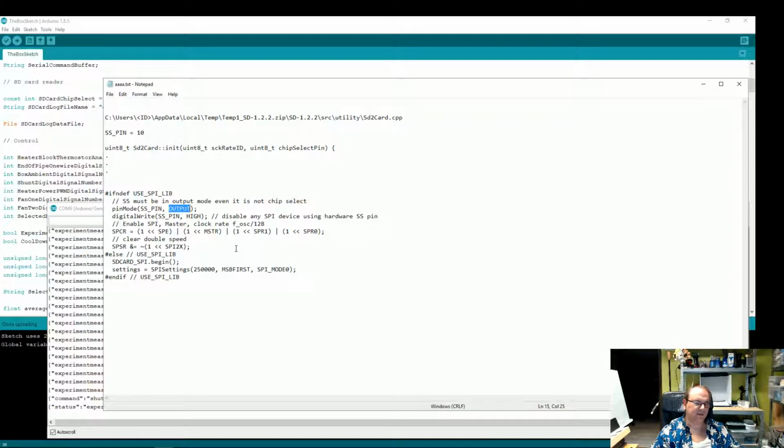And the thing is to untangle this low-level code. I mean, it doesn't do anything with the pin 10, because there's nothing connected to it, because on the higher level, you say what pin is the, I call it module select, because on the SPI bus you can have more than one module. So in this case, I tell it to use pin 4 to activate the SD card.